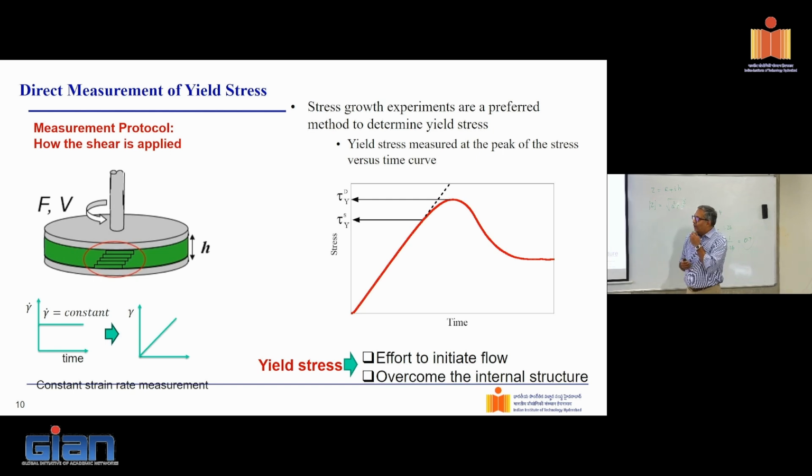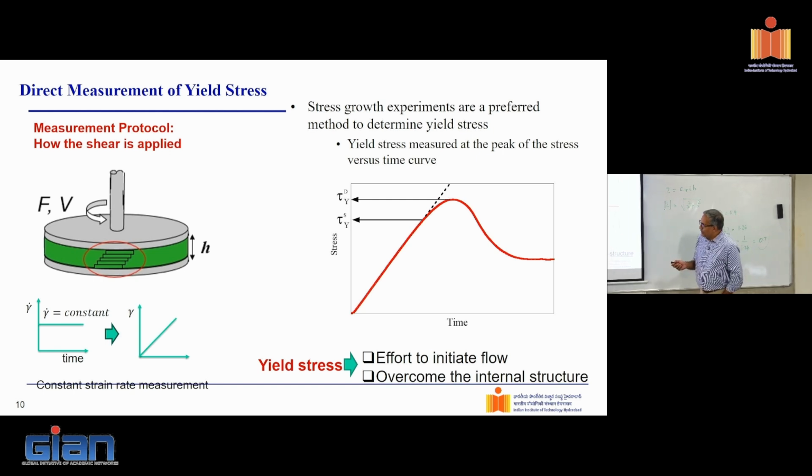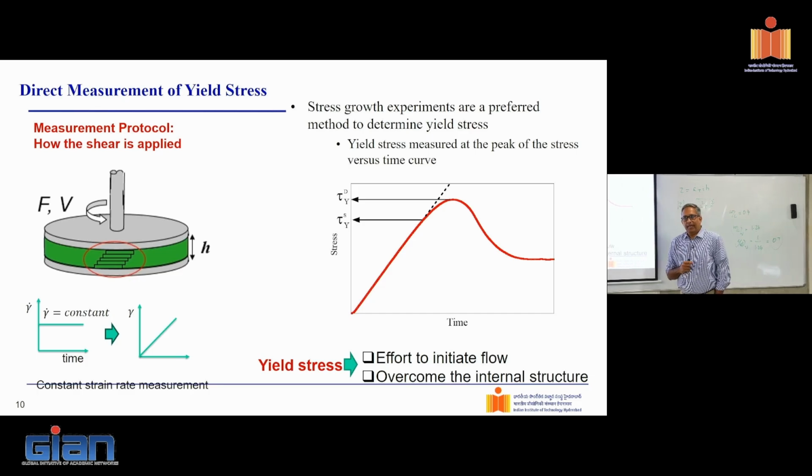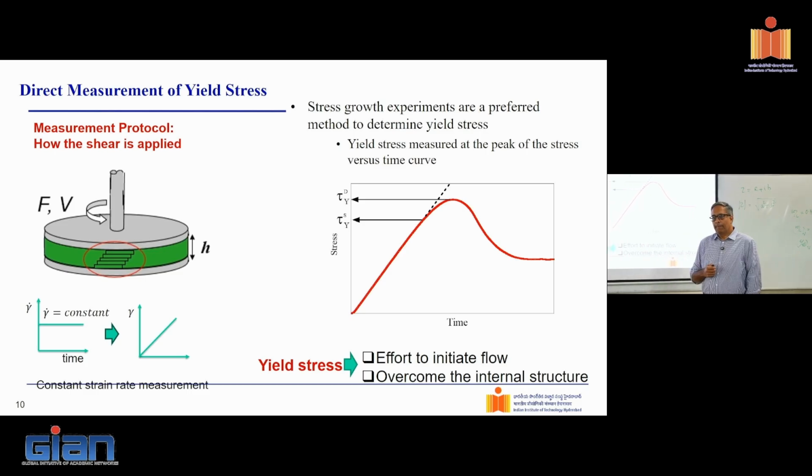Okay. Now, suppose I choose the parallel plate geometry. I've chosen this geometry, which means that if I'm using this geometry in a rheometer, it's calibrated. Right? So what does that mean? It is calibrated would imply that whatever torque and rotation I'm applying get converted into shear stress and shear strain rate, and I get those two. Now the question is, what protocol do I apply?